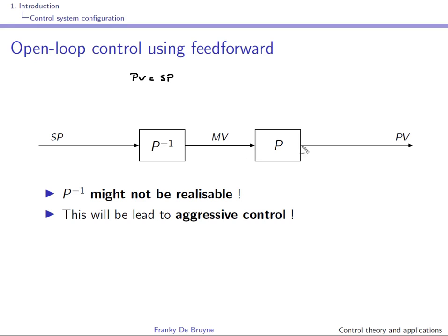And well, because of this dynamics, this will require a lot of control energy, and in practice this will not be possible because in processes, well, you have something that is called saturation, right? We have seen in the LTR 700 process and the TC Lab process that, for instance, the manipulated value, the heating power, is limited to 100%.